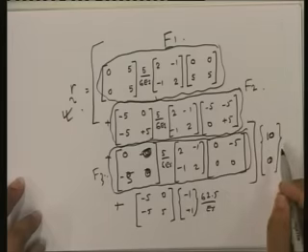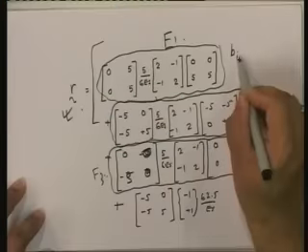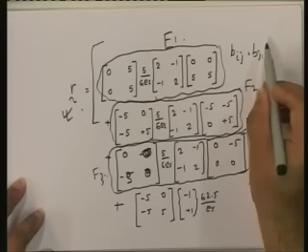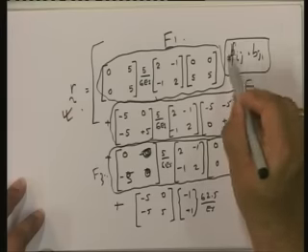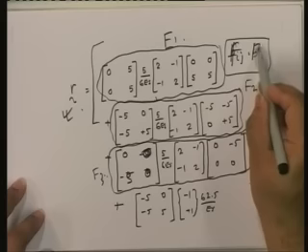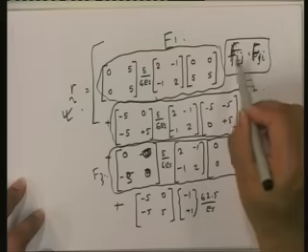Okay, and you will also notice something else, that in a structure flexibility matrix, remember the member flexibility matrix was what? 2 minus 1 minus 1 2 into L upon 6 EI. Did you notice something? It was symmetric. Okay, when you do these computations, you will see that the structure flexibility matrix is also symmetric. What does that mean? That Fij is equal to Fji.